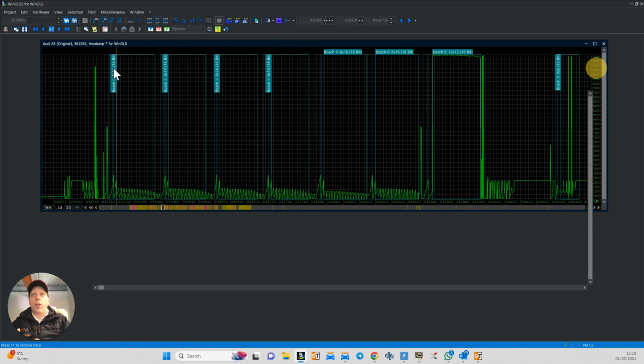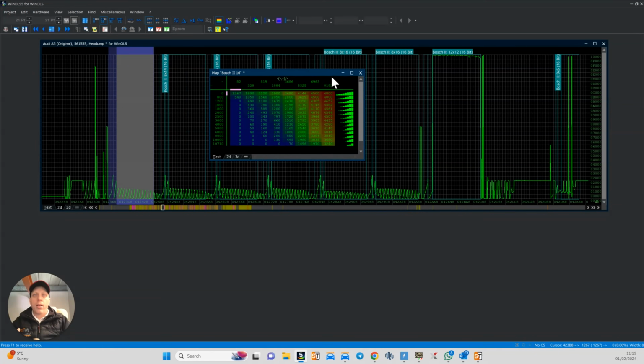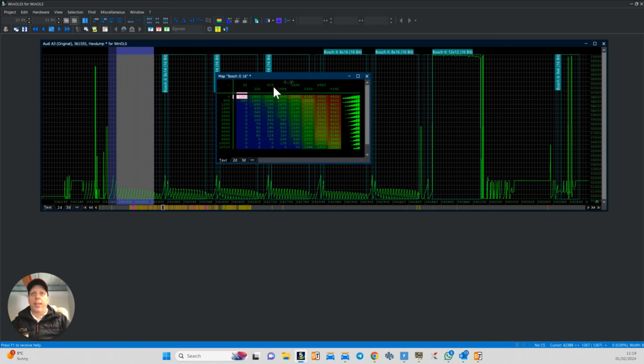And also, if we open this map up, anything in the map will be linked to other maps, or it could be linked to map axes. So you've got the axis up here. Nothing's done for us here. I know 8192 is 100%, and I know that's a throttle. So you've got throttle up top, you've got RPM down the side. Now, obviously, RPM doesn't make sense, so there's obviously factors attached to that too.